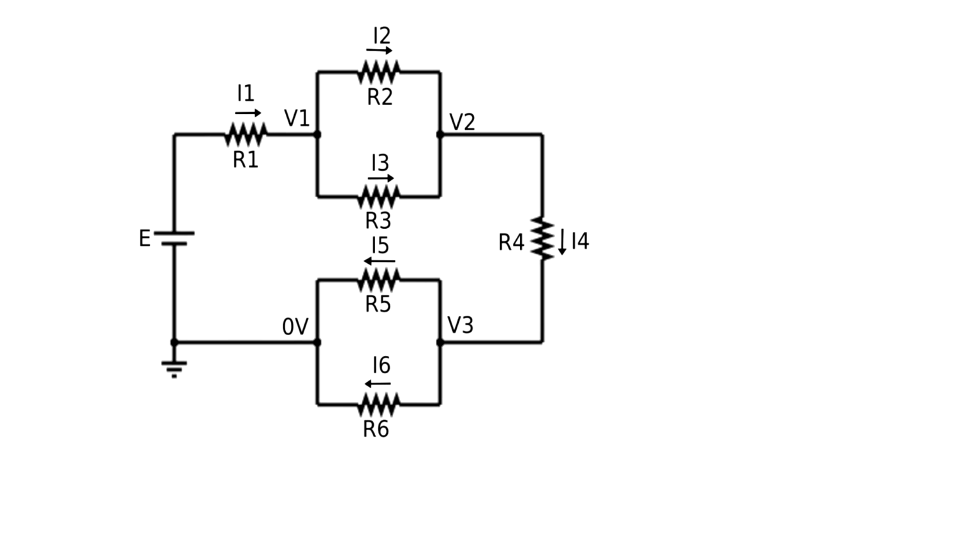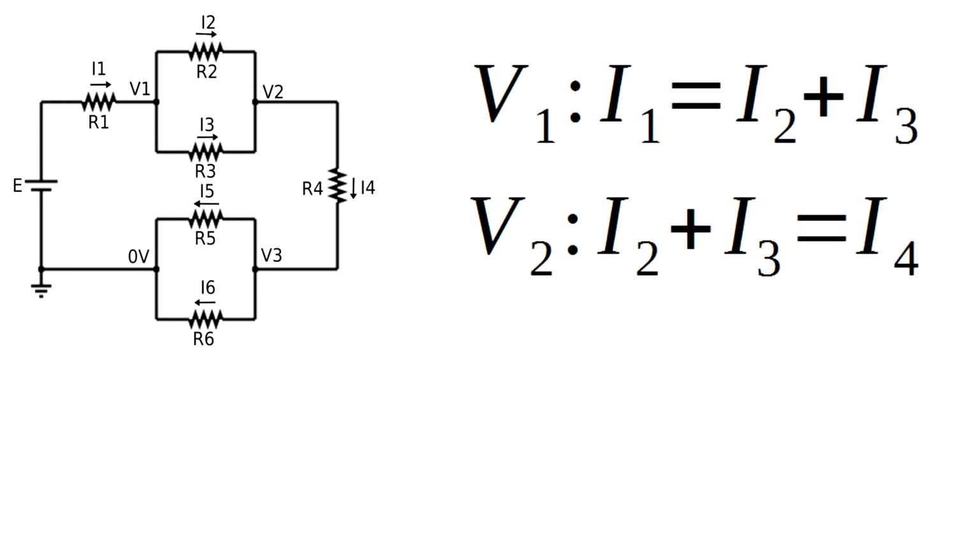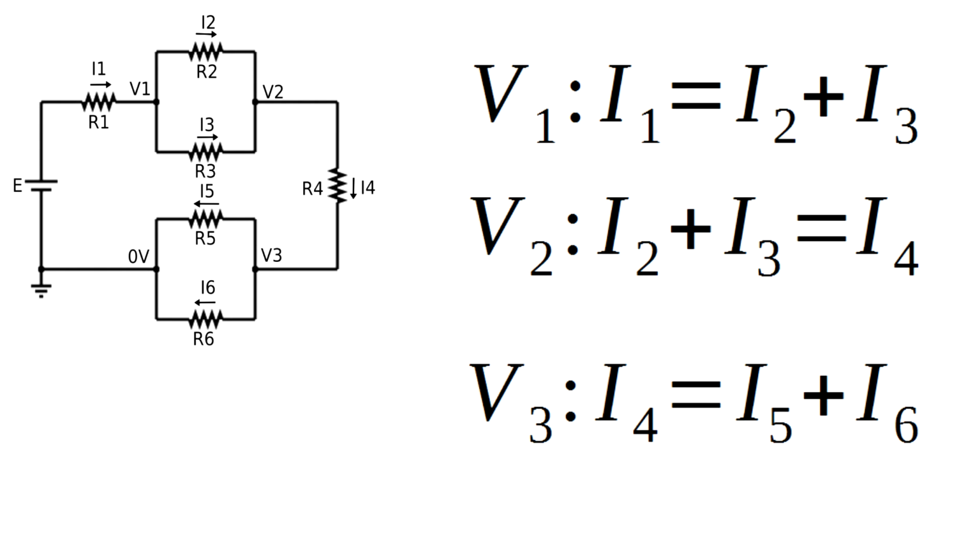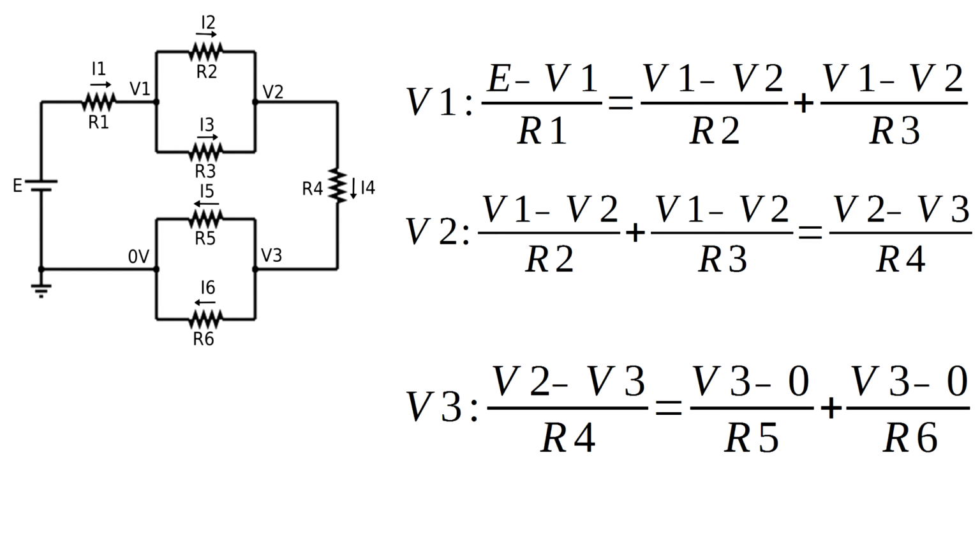So now that you have this, you make your KCL equations where entering current is positive and leaving current is negative, and then you just turn that I into a V over R, where the R is just the resistor value, and the V is just the voltage from minus the voltage to. Now, out of everything, that's probably the most difficult part to understand, so I'll explain that part in detail, just so you don't have an excuse to have no idea what's going on.